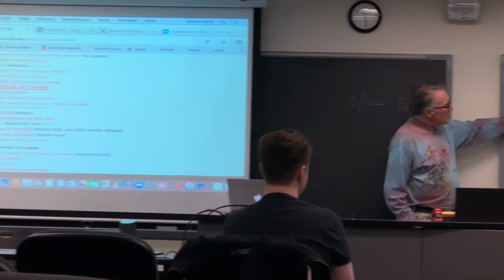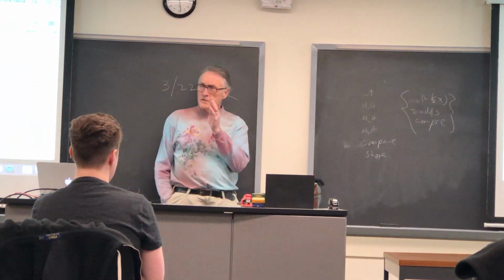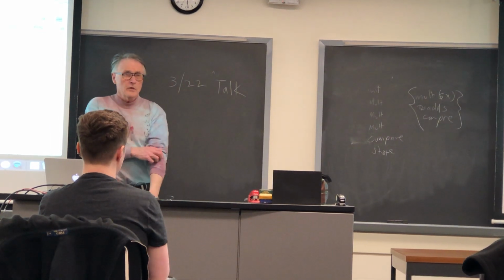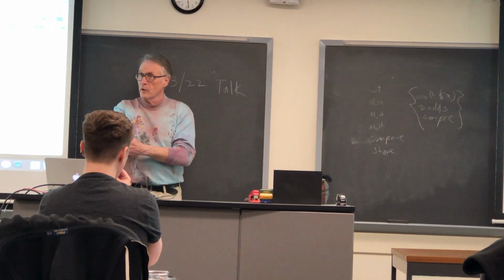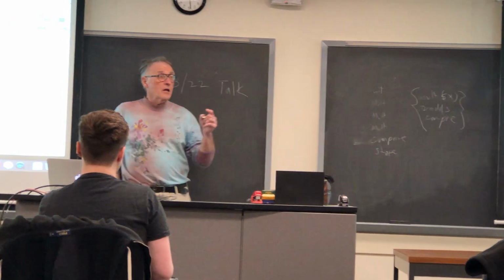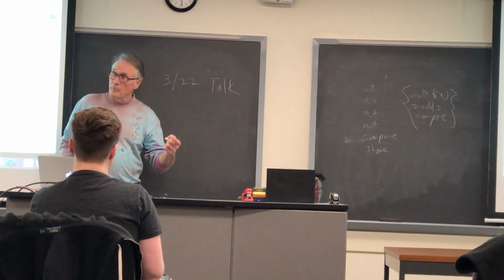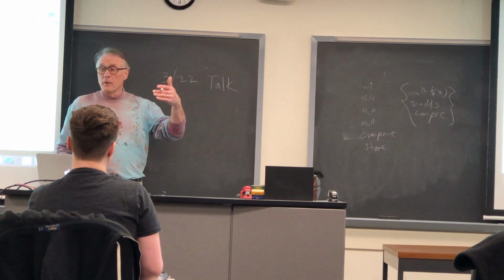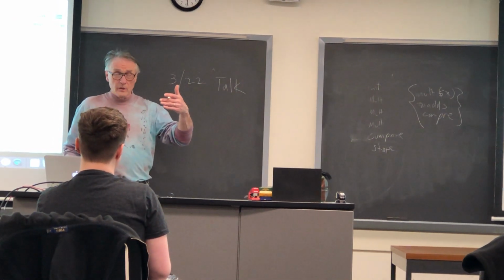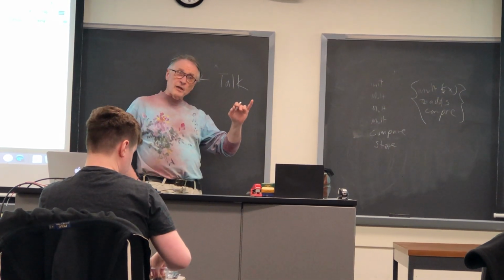If you pipeline this with a fairly limited number of operations per step, then you may well be able to run the clock faster. You can at least run it at clock 100. You can get a 100 megahertz clock by phase locking the clock 50 input up to 100, which is the preferred way to do it, because then you could say, I wonder if it'll run at 150.